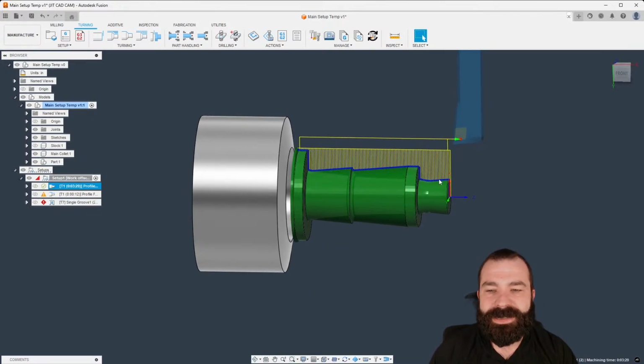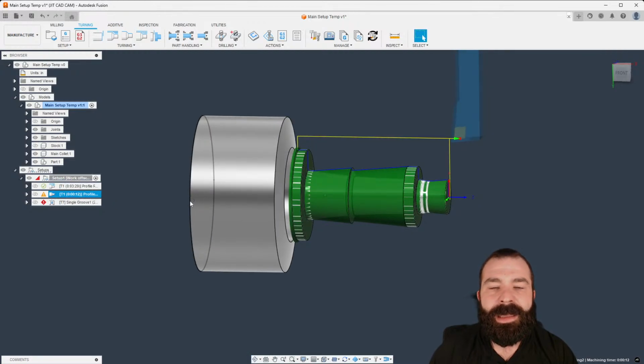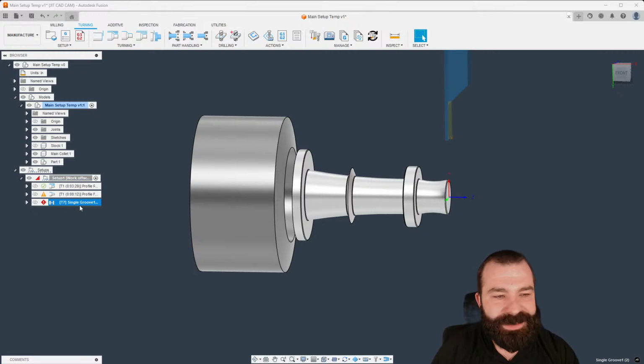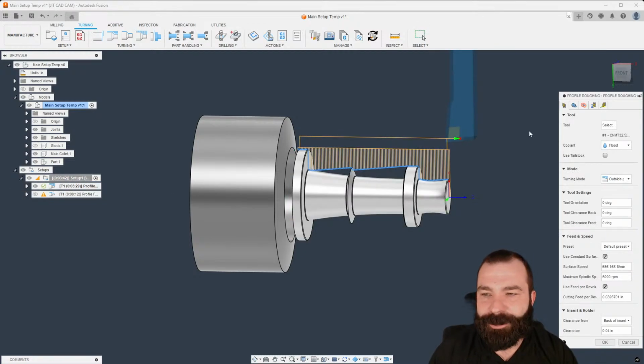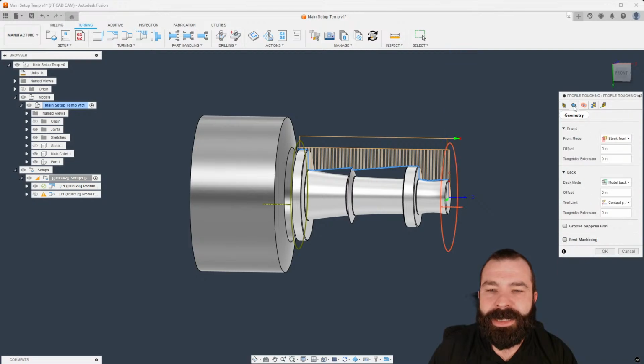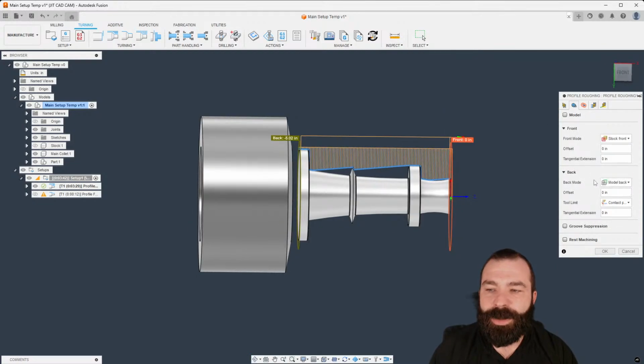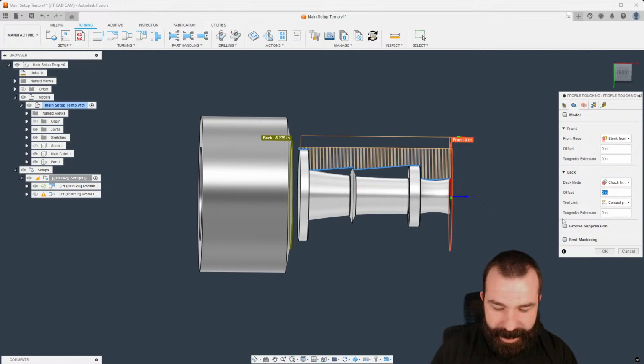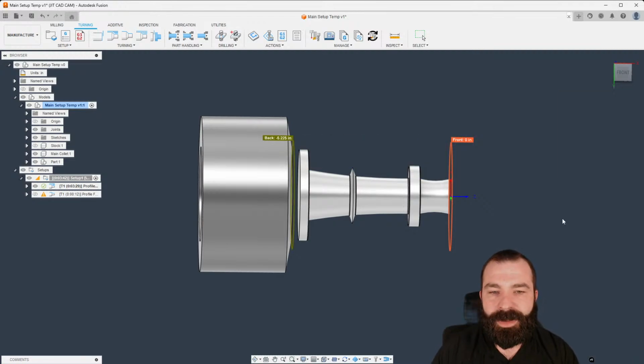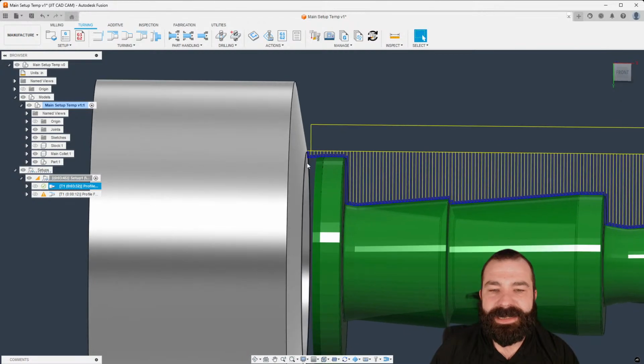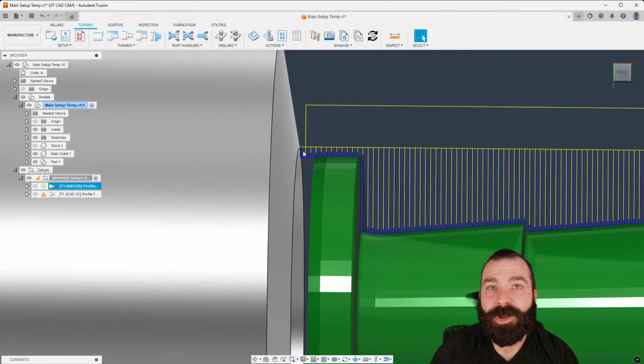And what you're noticing is they're now automatically referencing everything that needs to be done based on those profiles and those settings. Now, keep in mind, I do have single groove here. We wouldn't have a single groove there. We could also change some of the parameters here, where when we're talking about geometry, are we going to model back? Are we going to chuck front, staying away from maybe chuck front by 50 thou? Again, our idea is at some point we want to go in and part this off, right?